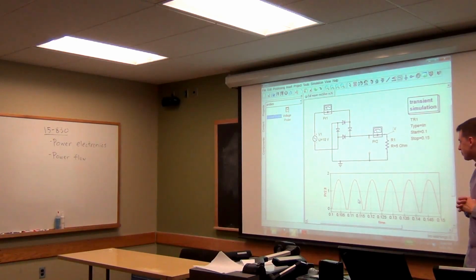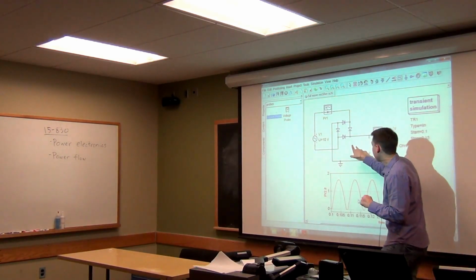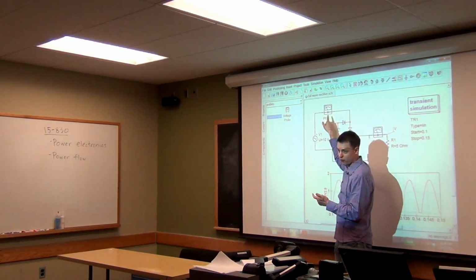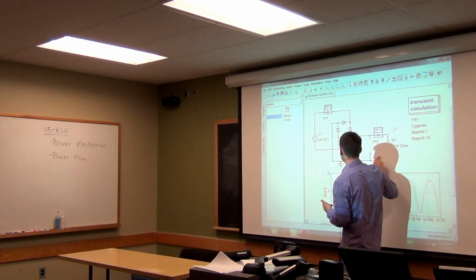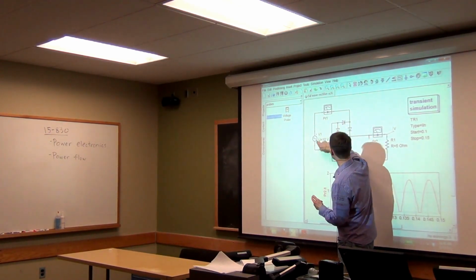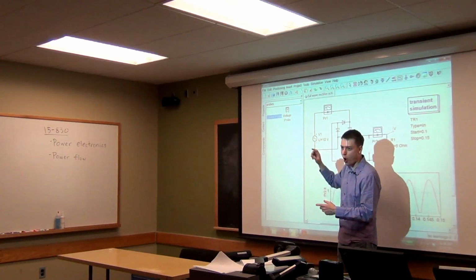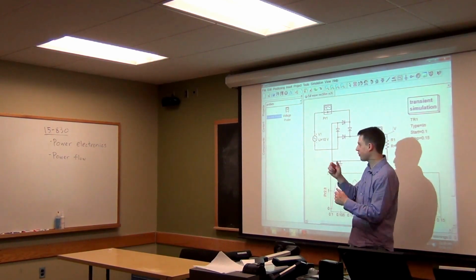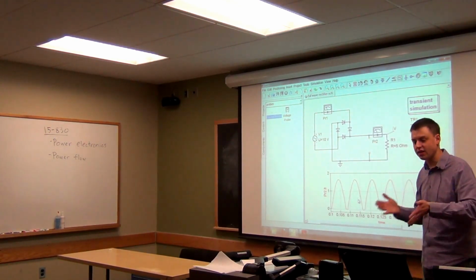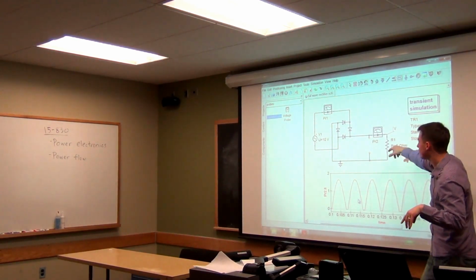So the reason why there's no negative part is because of the diodes? Yeah, exactly, because current has to always flow this way through the resistor by this full wave rectifier, right? If this is positive, it'll go this way. If it's negative, it'll go this way, right? It still goes through here. So it always goes this way through the unit, and that means the current always was positive from that sensor's perspective. And then the way you make it a DC source approximately is you just smooth this with a capacitor there.